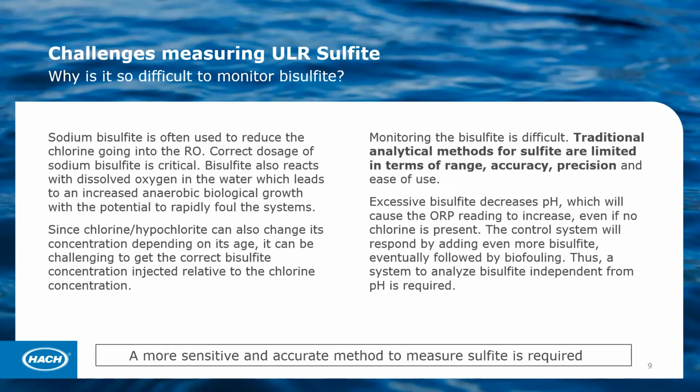And it is typically a reliable method as long as we monitor the health of those granular activated charcoal beds, and make sure we don't have any channeling happening in those GAC beds. It is typically reliable and has its positives in terms of no chemical costs, typically easy to maintain, and no additional chemicals after dechlorination to deal with.